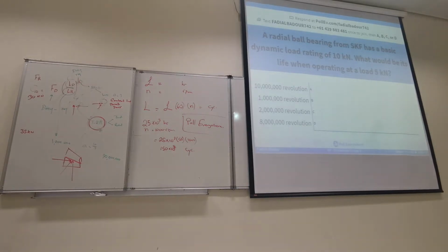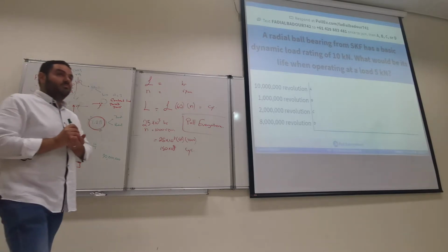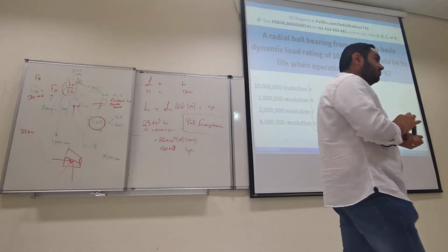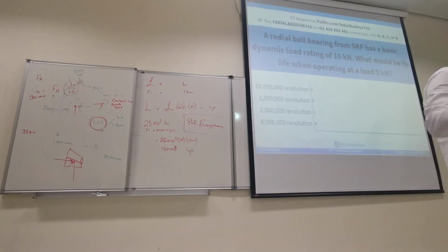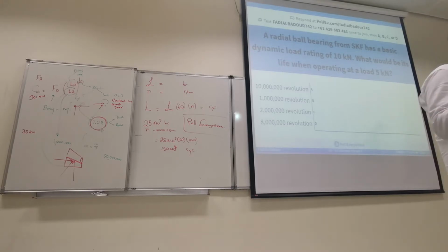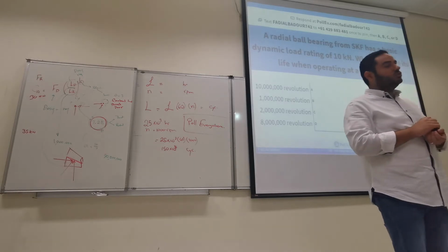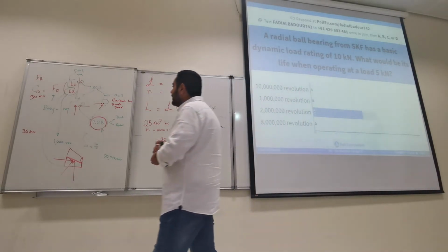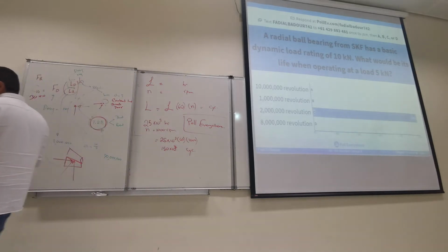Yes. You said the ball bearing is good to carry combined load, but poor with thrust. Tapered is good with both. How about this one? I said it can carry only pure radial load. It cannot have combined. Just only radial load. Which one is this? The cylindrical. Cylindrical, yes. Cylindrical can only carry pure radial load.